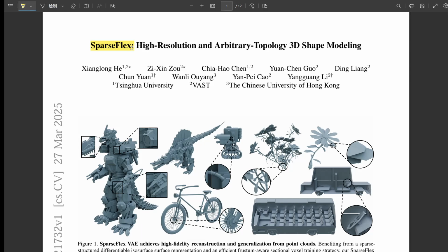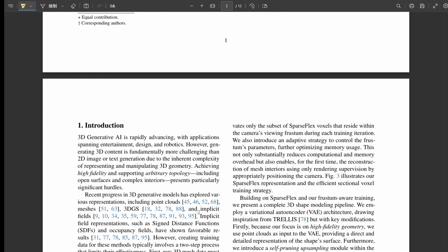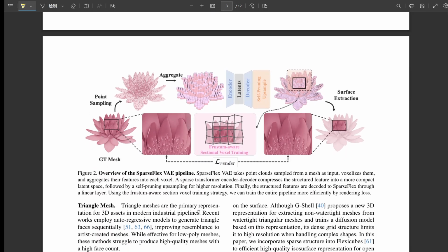Okay, that sounds like a pretty major drawback. What's the second step then? The second part is extracting the actual 3D mesh from these learned implicit fields, often using something like marching cubes. Now, that works okay sometimes, but the extraction itself can add its own little inaccuracies, artifacts, moving you further away from the original high-fidelity shape. Right. They also mention unsigned distance fields, UDFs, which can handle open surfaces better, but they often have stability issues during training, and they still struggle to capture those really subtle geometric features accurately. So we're kind of stuck between losing detail by forcing things closed or struggling with stability and precision if we try to keep them open.